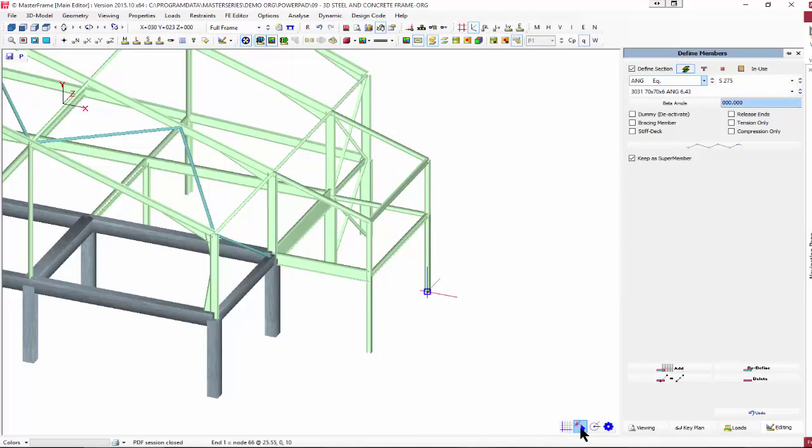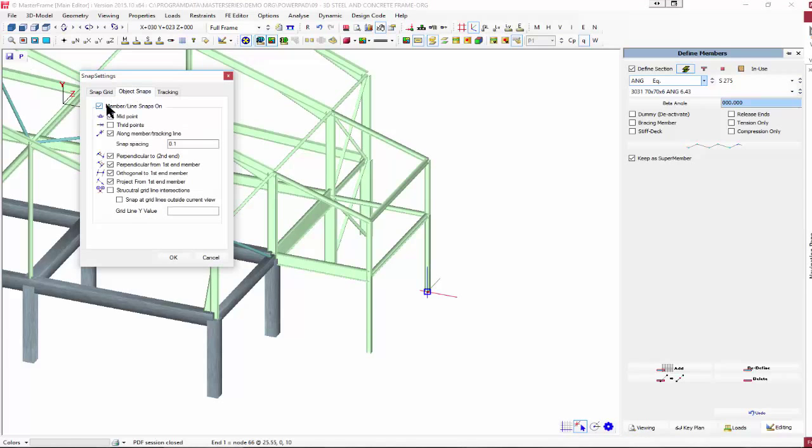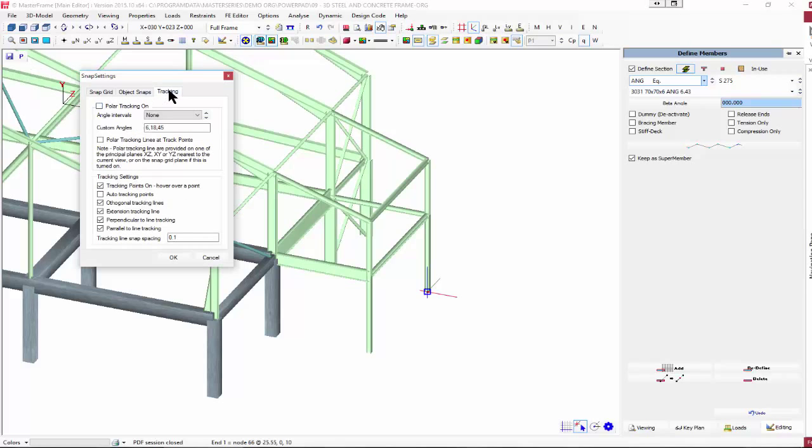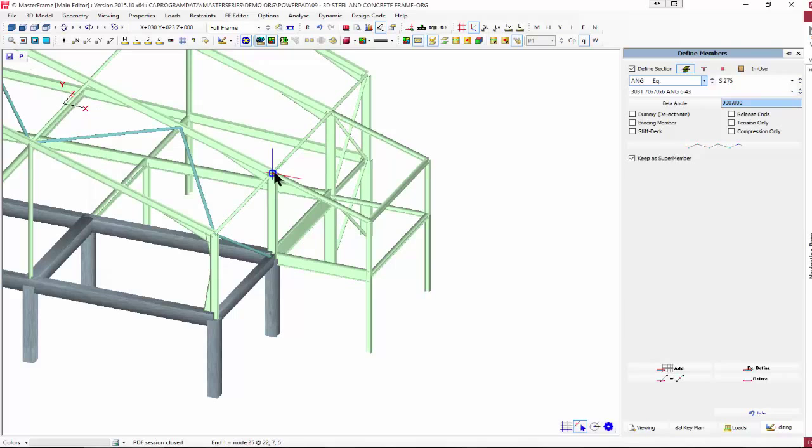And at this point, it's probably easiest if you try to turn off most of the snap points, so that they're only snapping to nodes. That just makes it that bit more accurate. And there, and some more bracing there, and there, but we'll portalize that ground floor.